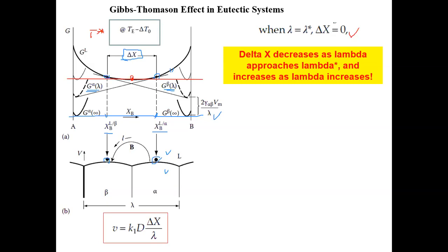So this basically means you have the critical nucleus, and that one will not grow. For the same reason that ice and water at T equals 0 degrees Celsius will never change, right? They're in equilibrium, they're both happy. None of the phases is more advantageous than the other, so they just remain that way. It's the same thing here. We show that there's no kinetics, so if I have a critical nucleus, it wouldn't grow.